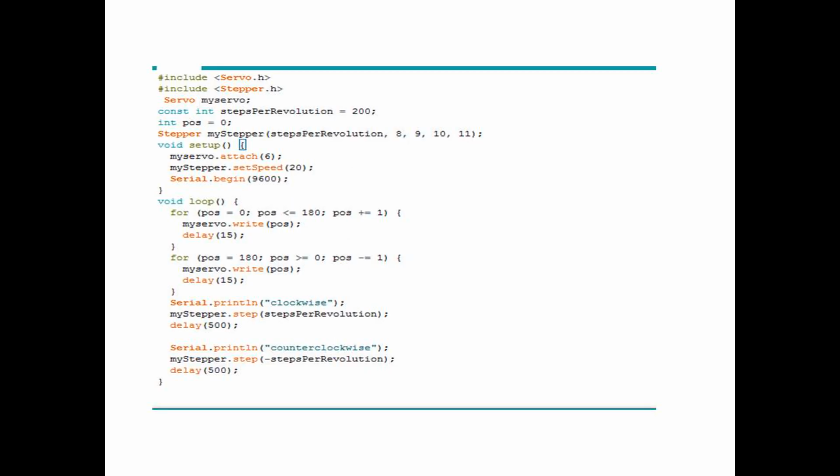Then let me explain the project code. Now you must be thinking how we are going to implement it. The idea is practical code and practical circuitry. So we use the Arduino microcontroller and download the Arduino software. When the LDR senses light, the servo rotates from 0 to 180 degrees, and the solar panel opens in its flower shape. Then the stepper motor rotates at 200 steps per revolution and 20 rpm speed to follow the sun direction.